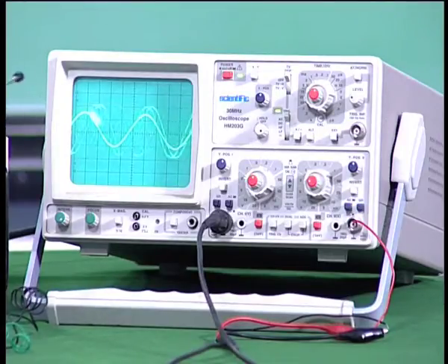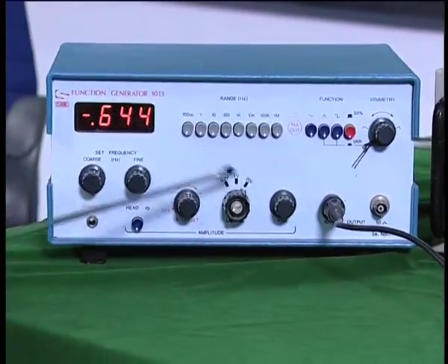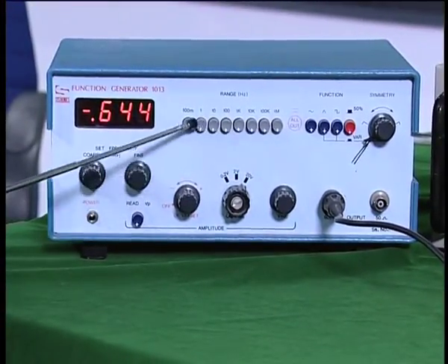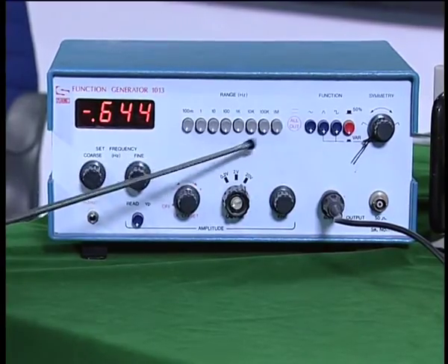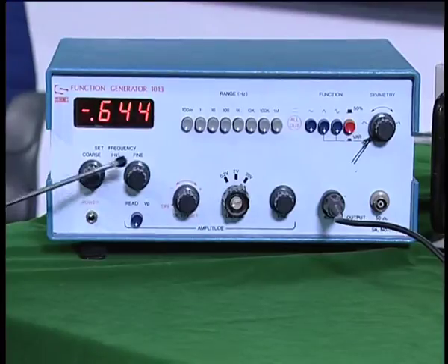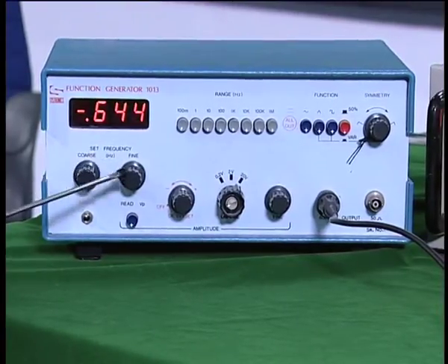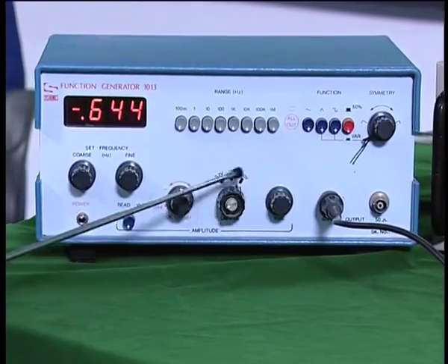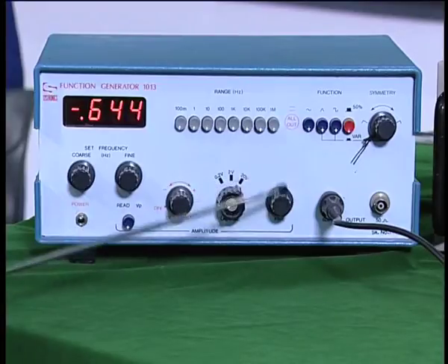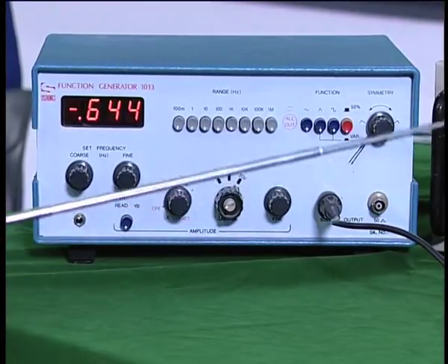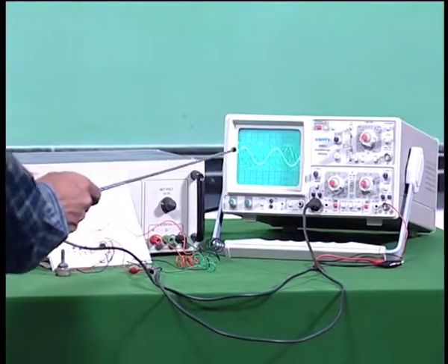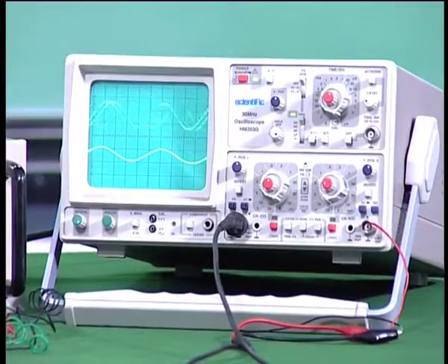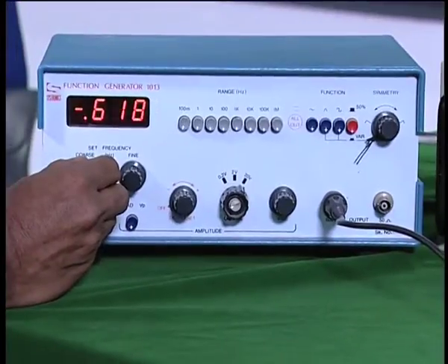To determine the frequency of oscillation, I am also connecting a function generator here. You can see that this is a function generator. So, you can select different frequency scales here 1, 10, 100, etc., and you can vary the frequency using these 2 knobs. One is for fast variation, the other one is for slow variation, coarse and fine, and you have here output voltage, again for coarse and fine. You can vary the amplitude, and the output of this I connected to another channel of the oscilloscope. In the oscilloscope you see 2 channels. I will show you.